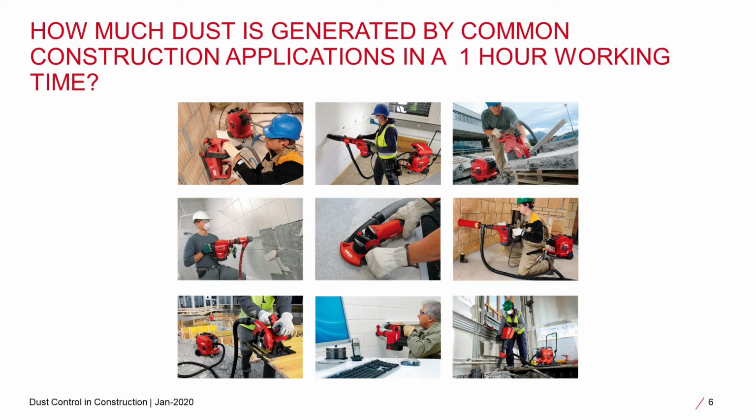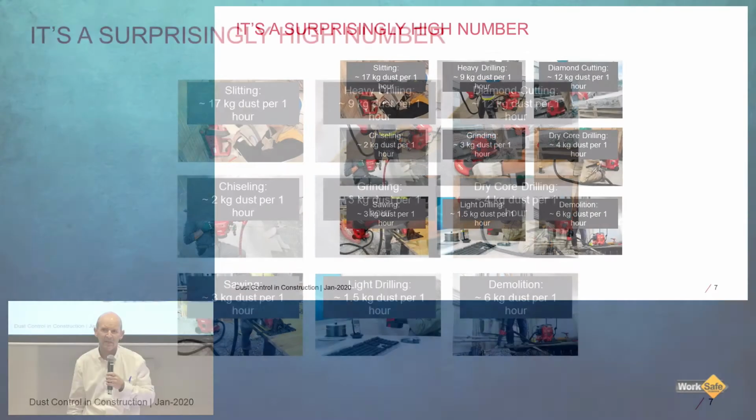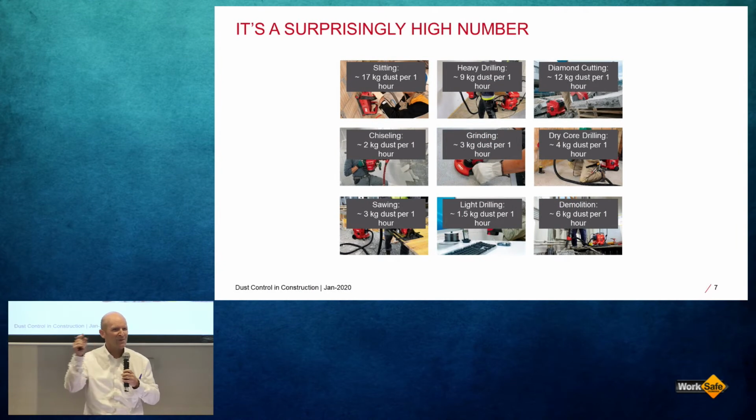So we see things like wall chasing, for example, that generates a huge amount of dust. So you simply can't do any amount of wall chasing without having dust extraction equipment fitted to that tooling. Another watch-out is heavy drilling. If you're drilling large diameter holes, maybe you're doing post-install rebar or large anchors, that's another watch-out because it really does generate a huge amount of dust. So that's how we're linking the medical science to the practicalities of what you see on site.